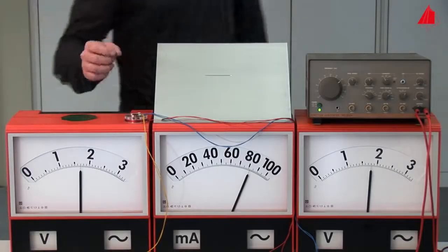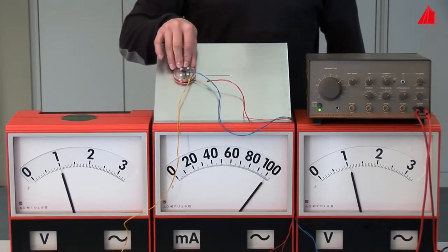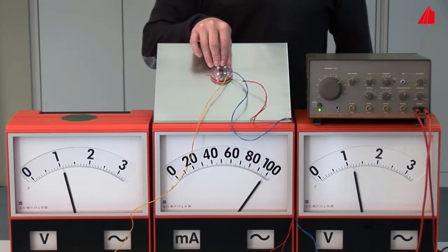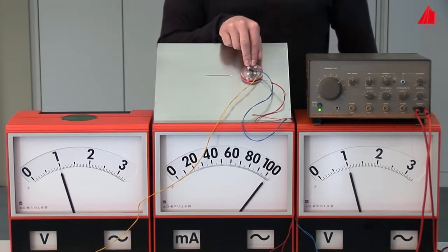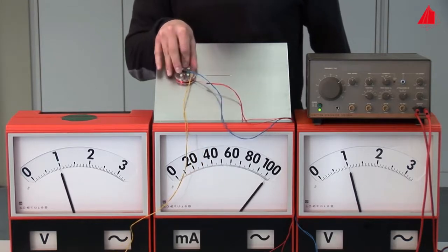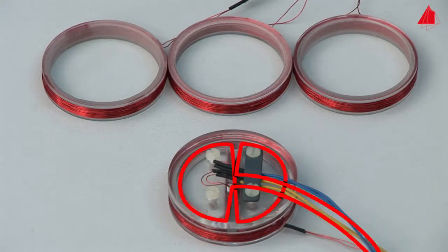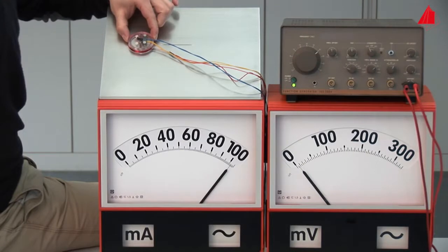When testing this coil set in the laboratory, we are initially disappointed. Firstly, already in the intact region of the sheet, a high voltage is induced in the receiver coils. This is because the receiver coils are now positioned within the excitation coil. Secondly, the saw cut is only faintly detectable. Now we use a trick that we have already applied to the coaxial probes. We switch the receiver coils against each other and only measure the voltage difference between them. Now everything works in a way that suits us.